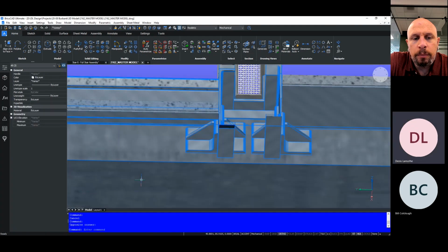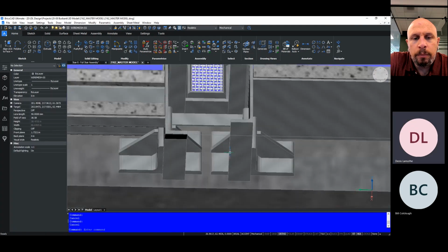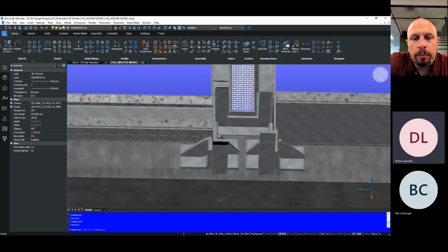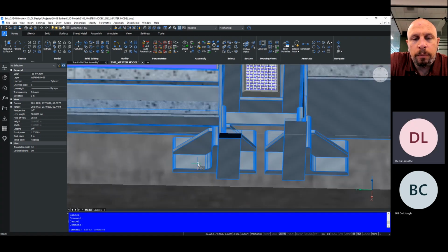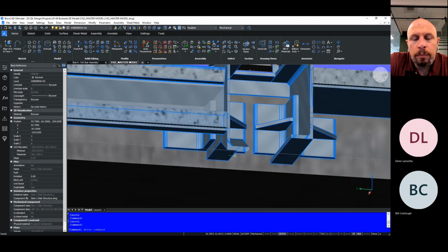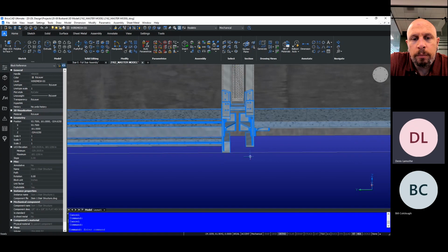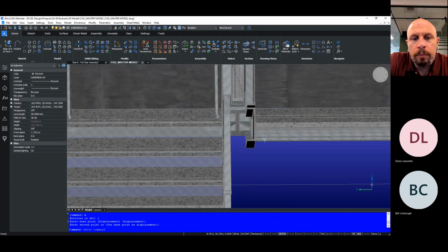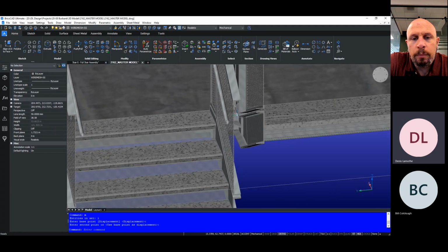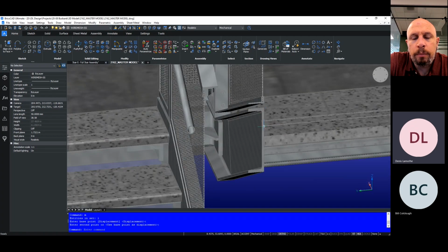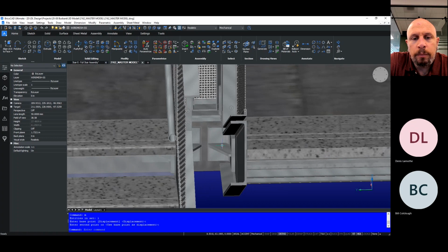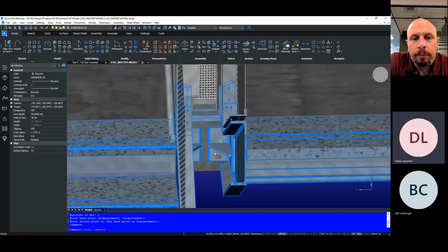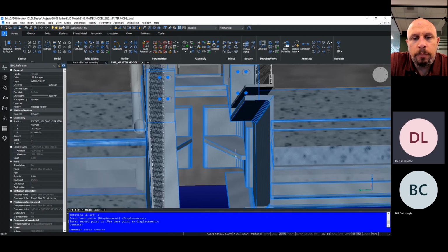Well, we had a continuous steel embed plate, and so we were able to field weld these clip angles at the top of the stair connections. We could do the same thing for the next flight of stairs going up to the next level, because they were tying into the side of the cutout opening in the slab. So that illustrates a little bit how one system can be used.